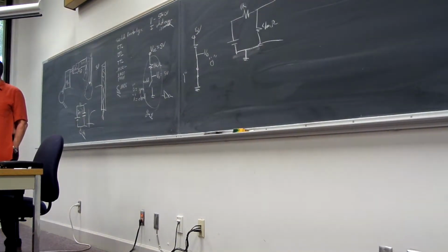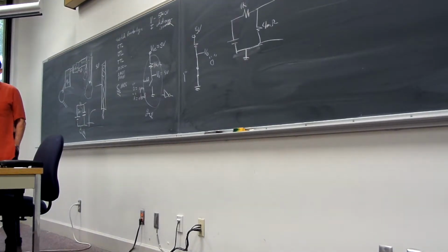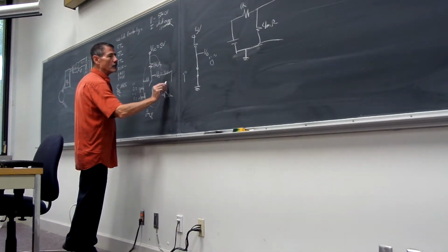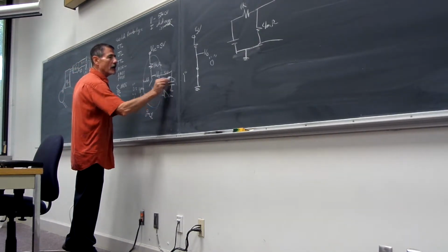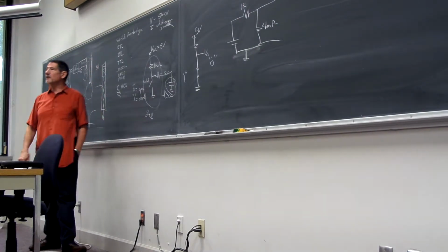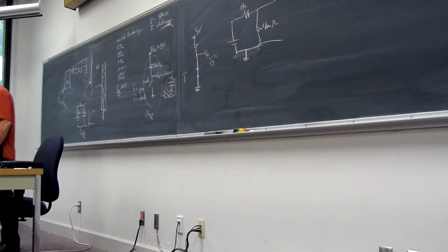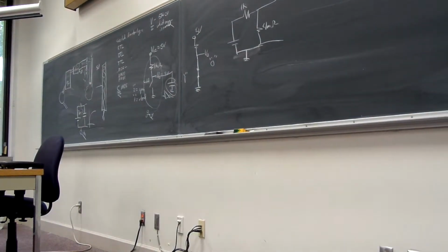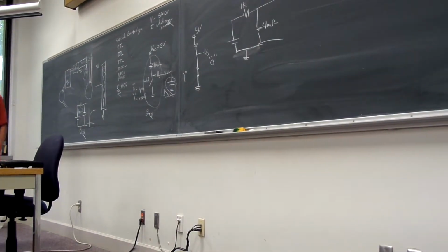We'd really have low power at that point, correct? The only downside with doing this is that when you drive another gate, we're going to see that most gates have some type of input capacitance. And so if you start jacking up the resistor too high, what happens to the rise time of our signal or the fall time? Remember, we were talking about blowing up the balloon over there?